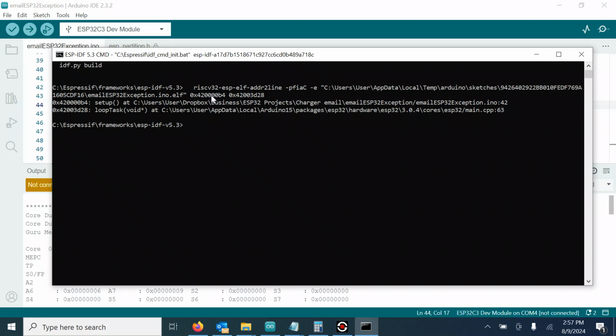So when your software crashes, you could save it in Flash on a reboot, because it'll automatically save the dump in Flash, and email you saying we had a crash at this location. Then run this little tool, and you can see what's happening in your code, or at least what part of your code is suspicious, doing divide by zeros or bad addresses or whatever.